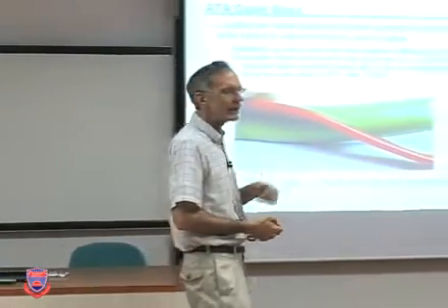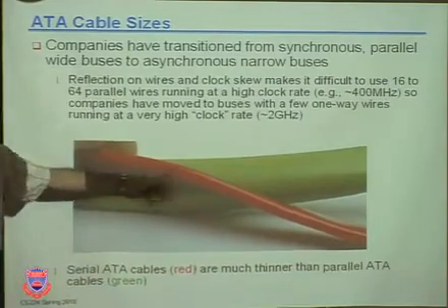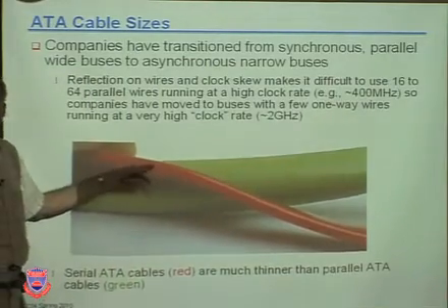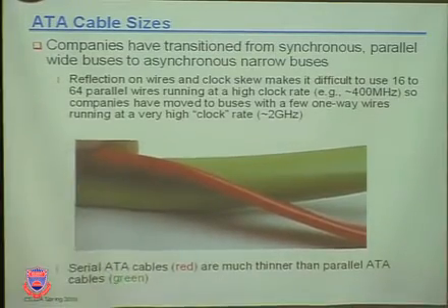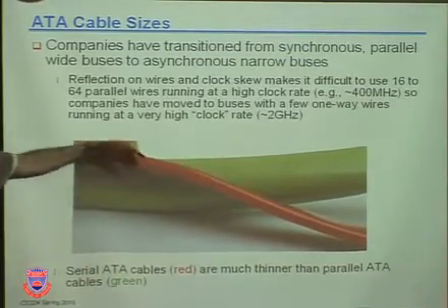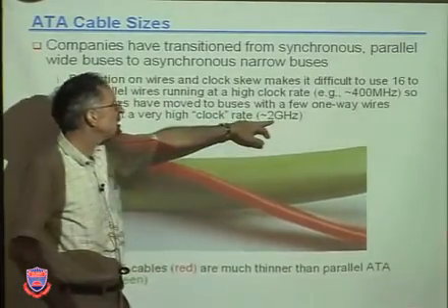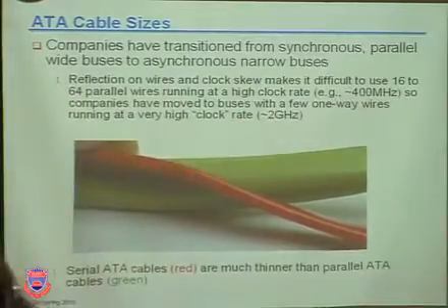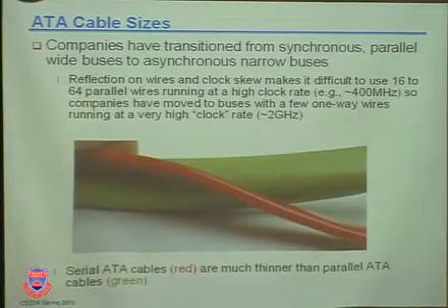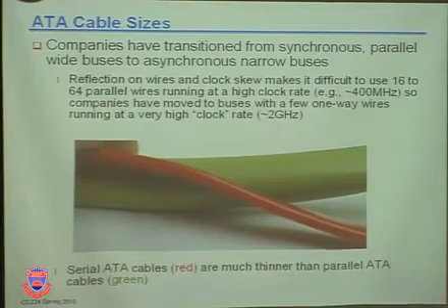So serial buses tend to be way faster in clock rate than parallel buses, okay? And also much thinner and cheaper. So how can you lose? Smaller, lighter, thinner, more flexible, less costly, and faster data rate. Win-win. Thank you very much. Okay? Look at the combinations here. You can run these serial buses at extremely high, 2 gigahertz clock rates, and the parallel ones are sort of limited because of their massive number of wires. So as a consequence, when you try to do 64 wires in parallel, you just can't get higher than, you know, megahertz range.